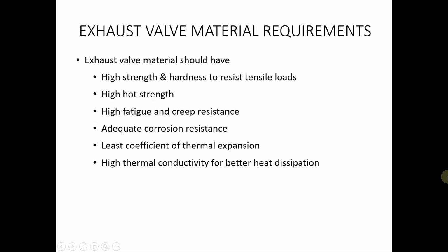And due to these high temperatures, the exhaust valve should be made of materials which can withstand high temperatures as well as the stress conditions at higher temperatures. So it should have high strength and hardness to resist tensile loading. Tensile loading occurs due to the spring loading. It should have high hot strength.